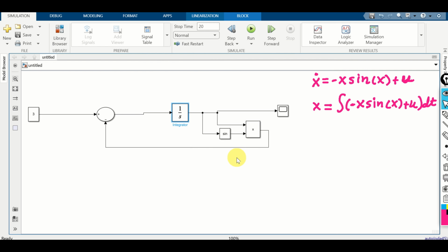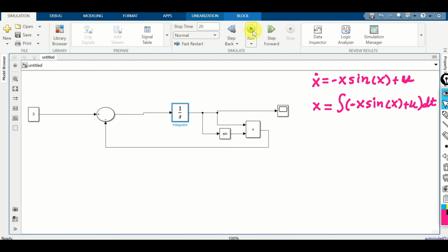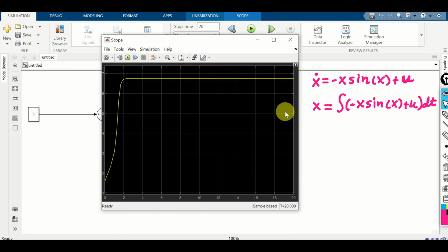Again, to repeat, Simulink by default linearizes nonlinear systems around initial states. And we can change this later on. However, due to the brevity and simplicity of this tutorial, we'll just use the basic settings. Okay, let's now run the simulation and let's see the output once more. Here it is. Good. We see that we start from approximately pi over 2.